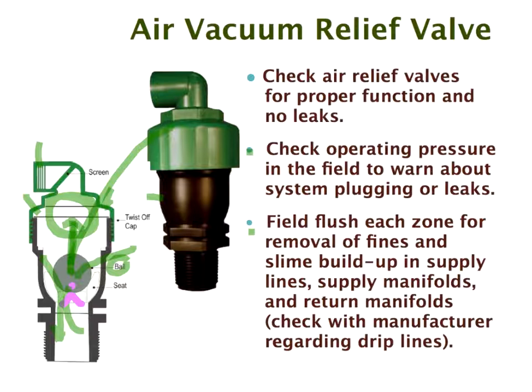But I don't see how, under vacuum, if it falls down and is sealing here, it's going to let the air in, so it has to allow the air back in through a slit. The ball has to move up to let the air out. Under water pressure, it's going to stay up. So under vacuum, it falls down and then has to have a leak here to let the water flow out. Correct?